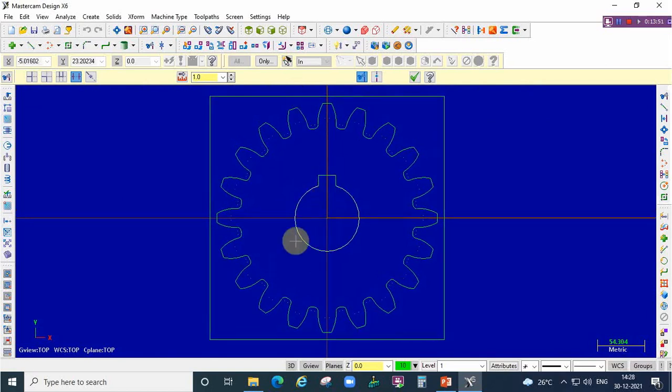After this, the very important point is creating the thread point and cut point. For wire cut EDM process, there will be a hole outside as well as inside. Through that hole only the wire goes inside the profile. The wire is inserted and will move around the profile. After completing the EDM process, the wire has to come out through the same hole or another hole. For that, one thread point and one cut point will be created.